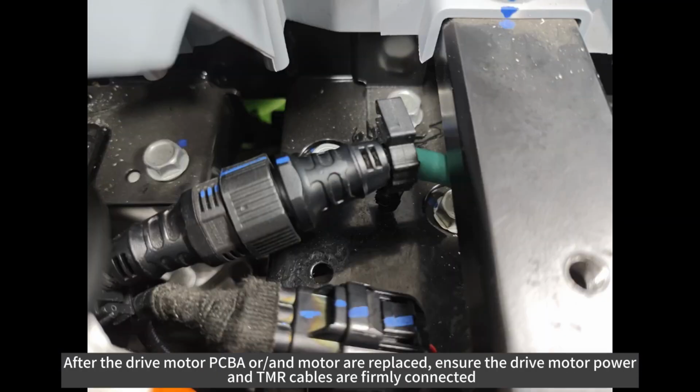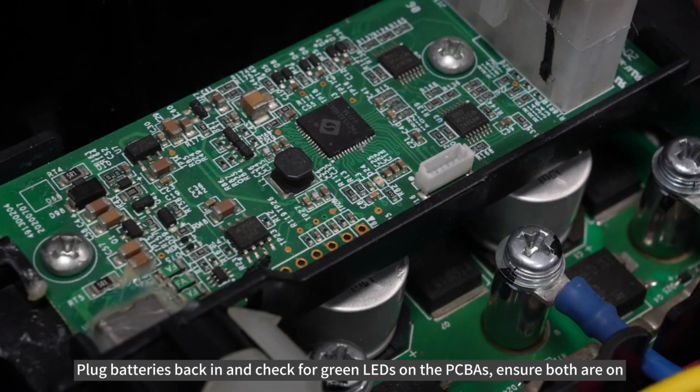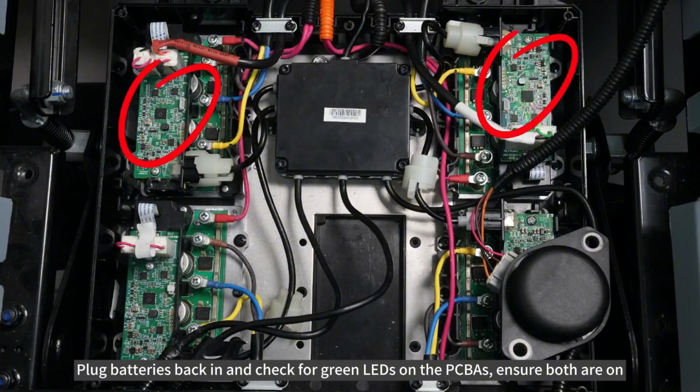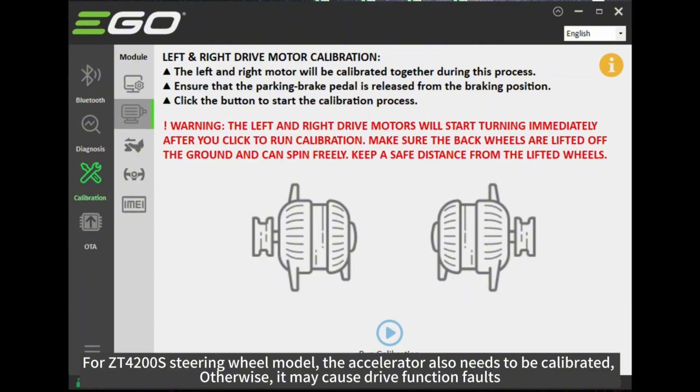After the drive motor PCBA and/or motor are replaced, ensure the drive motor power and TMR cables are firmly connected. Plug batteries back in and check for green LEDs on the PCBAs. Ensure both are on. After the replacement of a drive motor PCBA, please ensure the firmware is updated and the drive motors and lap bars are calibrated. For ZT4200S steering wheel model, the accelerator also needs to be calibrated, otherwise, it may cause drive function faults.